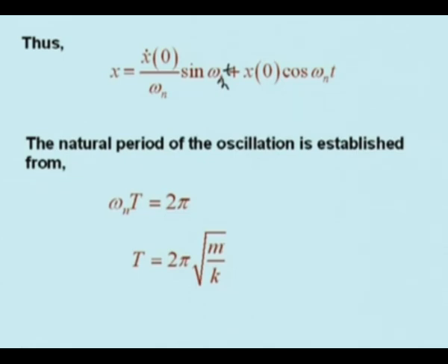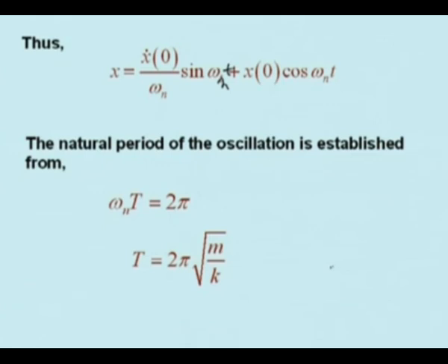If you take a spring mass system and suppose the spring is very stiff, k is very high, then the time period will be almost 0. That means the motion will immediately come back to the same position. So the time period is 0, it vibrates, and if k is very small, then the time period becomes very high, and similarly for the mass.